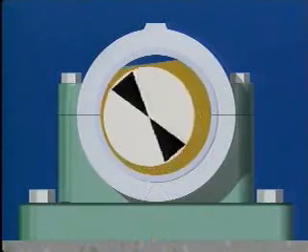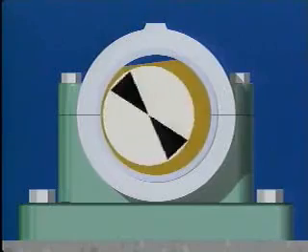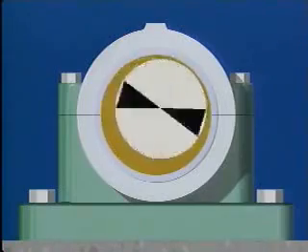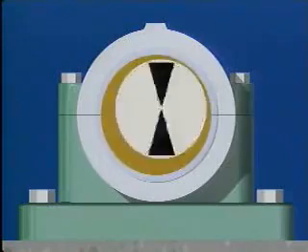But when the equipment is started, the shaft begins to roll slowly, and the motion drags oil underneath the shaft. Oil sticks to the shaft as the shaft turns, and the oil is carried between the two surfaces. The shaft is lifted away from the surface of the bearing by a film of oil. As the rotational speed increases, more and more oil is drawn under the shaft, and eventually, full film lubrication is achieved. The layer of oil supports the shaft and prevents it from touching the bearing surface.